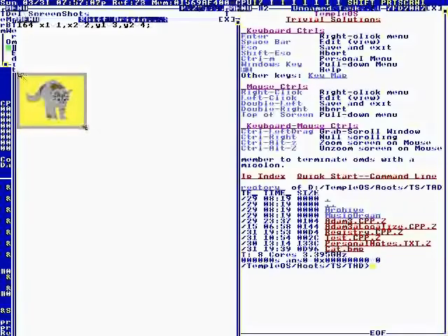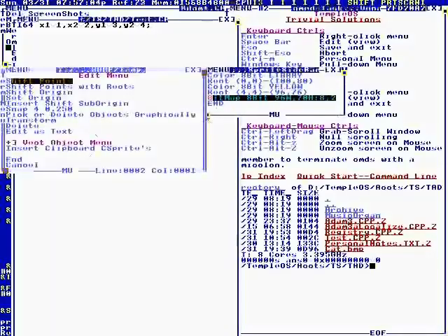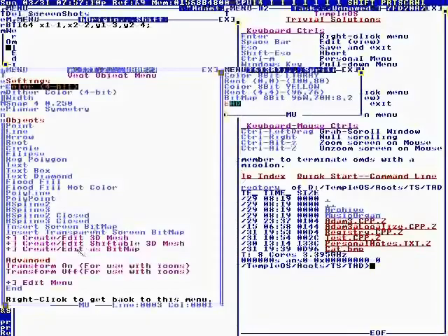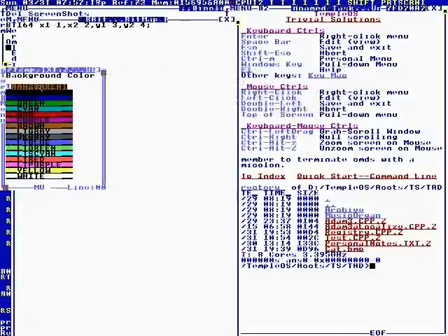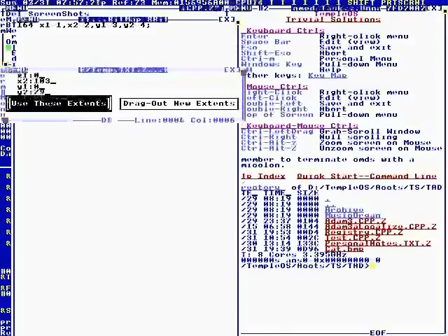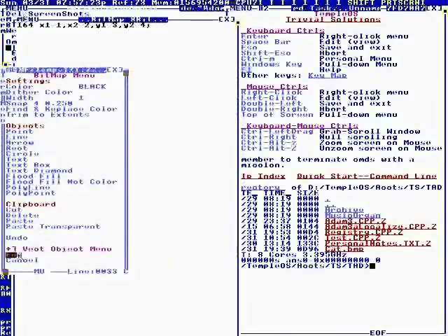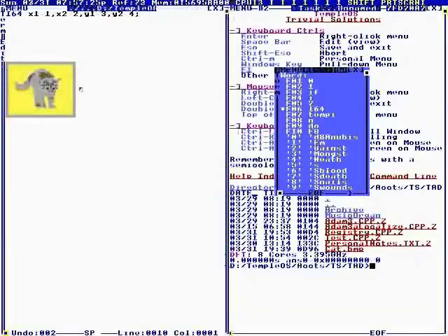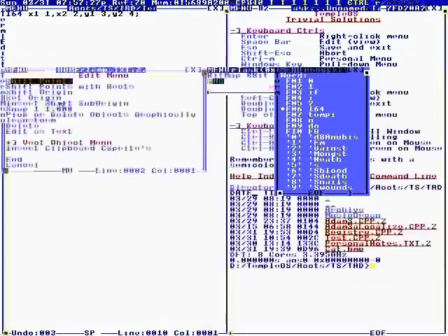Okay, now I want to merge these. If you put it on end and you go to the vector menu and then you go to create edit bitmap, this will merge. If this is on end, your insert point, then this will merge them. Use extents. I merged them into one bitmap.